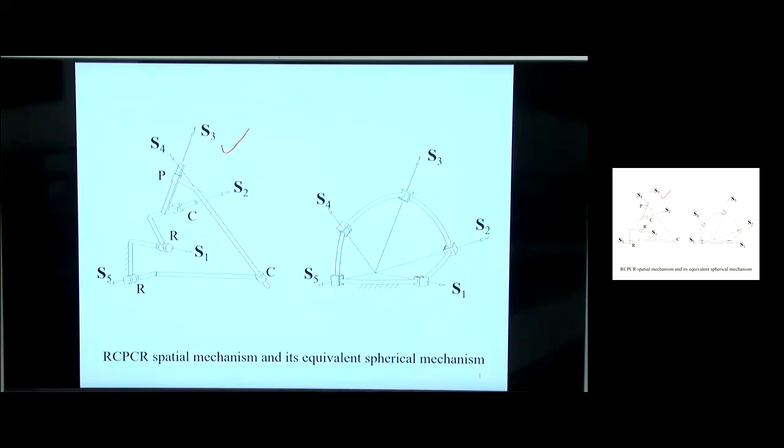On the left, if we check the mobility, it had better be 1 degree of freedom. For the closed loop mechanism, because the number of links equals the number of joints, the mobility is the sum of the freedoms of the joints minus 6. I've got 1 freedom on the revolute, another one that has 2 freedoms, so it's 4, 1 freedom is 5, 2 freedoms, so you get 7 minus 6 is 1. So this definitely is 1 degree of freedom.